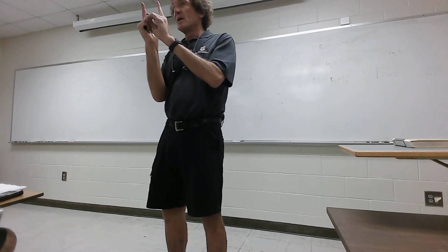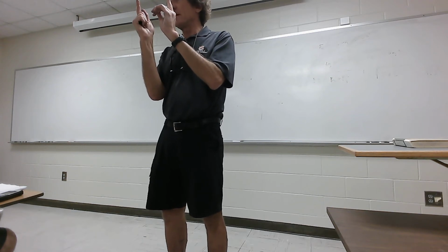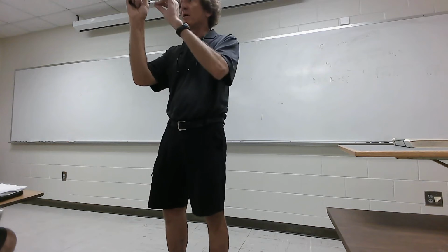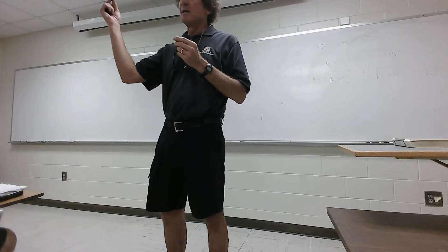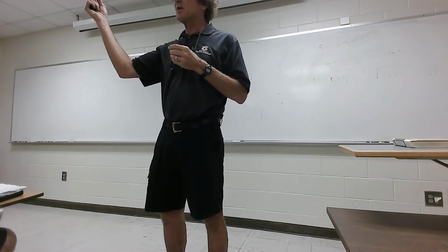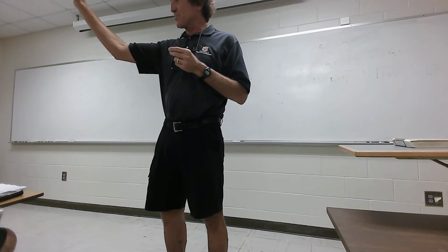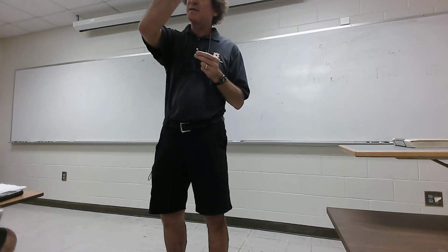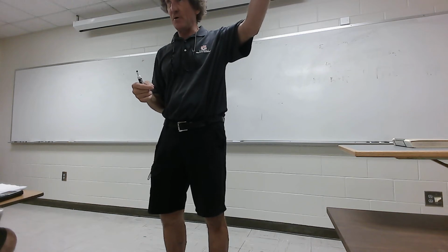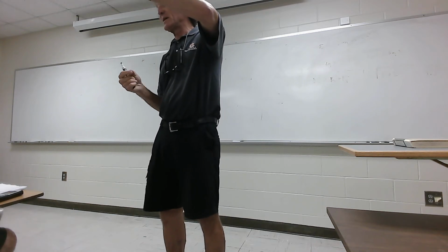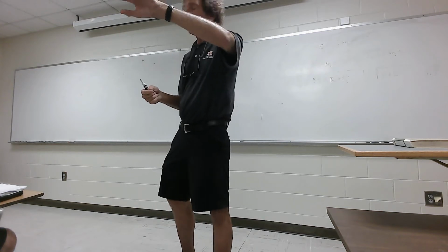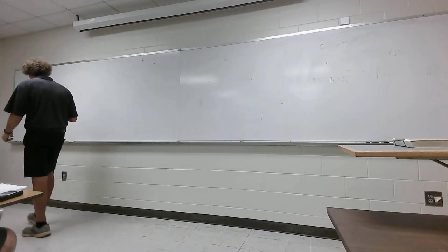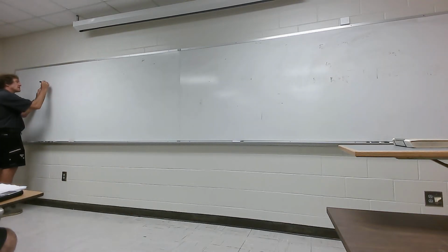In a dielectric, you'll get these things. They're not going to move, they're in place, but they're gonna wiggle back and forth and cause a frictional loss and heat it. That's a loss, but it's not real current. When you talk about J or sigma E current, it means actually if you could spray paint that electron, it's gonna flow through the lattice and go to the other spot where it's trying to get to. You all follow me? But when you have a dielectric with dielectric current losses, the dipoles just wiggle and heat up, and that is the reason for the loss. So here's how we do it, and I'm not gonna spend a whole lot of time on this. But normally, when you have curl of H, so this is gonna be low loss dielectrics.